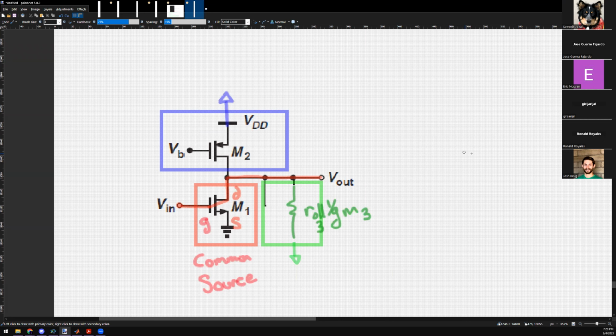Right. So for diode connections, it's just a resistor. What about this one? What impedance am I looking into? This guy is a 2-terminal device, right? VB is not part of the signal chain. It's just a bias voltage, so this is AC grounded. From the signal path perspective, I want to replace this guy with the impedance looking into it. So which device am I looking into? Which terminal? The drain.